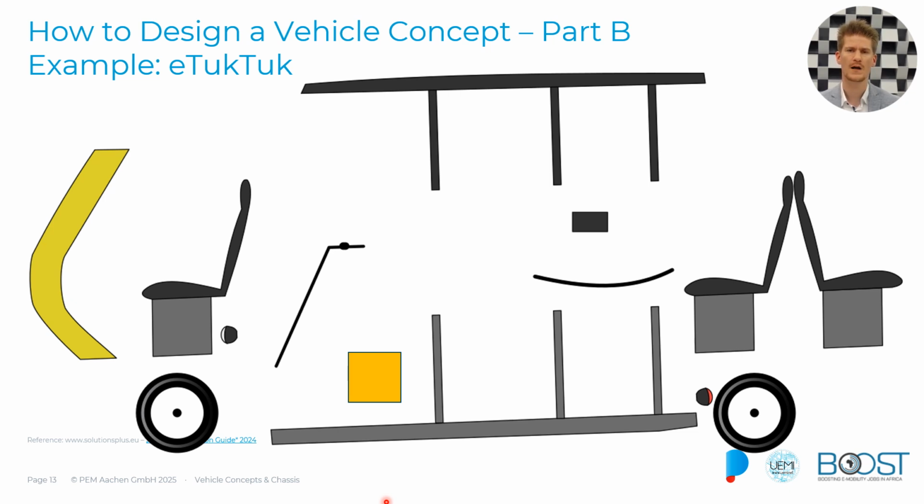And we can go a little bit into further detail with our domains. So I talked about the chassis, so the chassis will consist of our framework. This is the base frame down here. It will also be part with the rear suspension and the front suspension, while, for instance, the electric motor is rather on its own, but has to correspond with the battery and the battery management system, so the BMS for the energy storage. And if we look at the body structure, we will see the driver compartment, so this shield at the front, but also the seats.